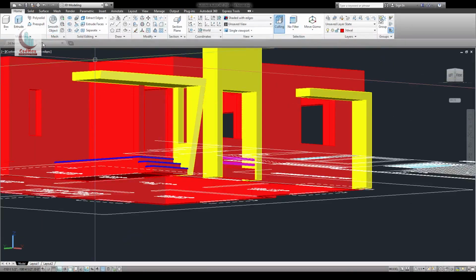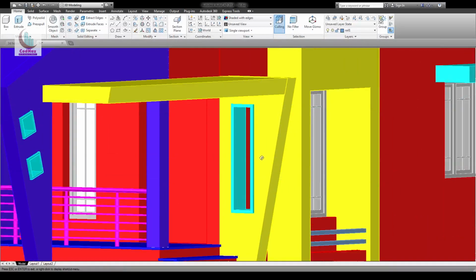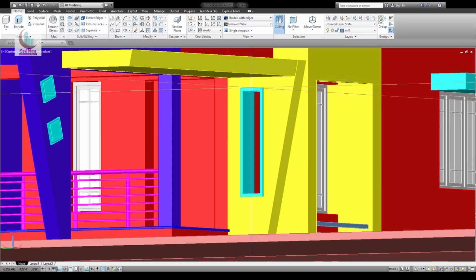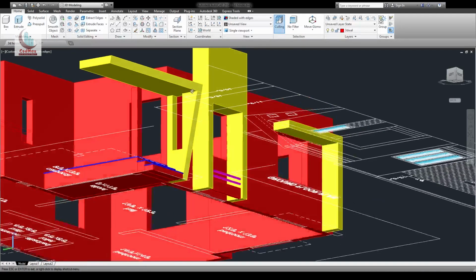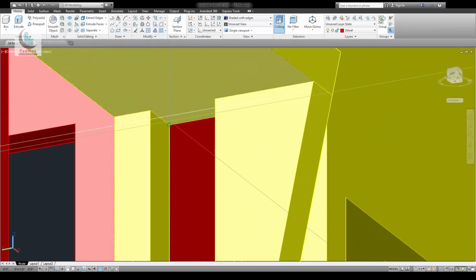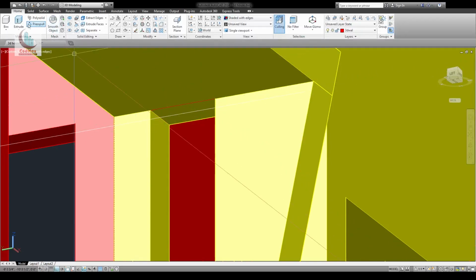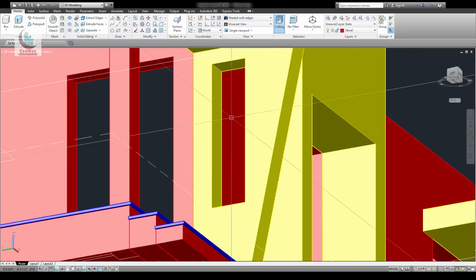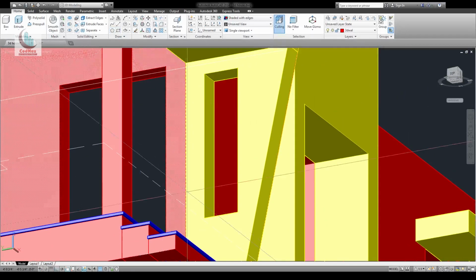Okay, and here there is a band, like this plastering band, and also the opening is slightly less, that is by 6 inches less. So we have to draw a rectangle here. Okay, extrude that by say -6. Now this is separate and this is separate. You can join those two. Go to union, select this one and select this. It is joined.